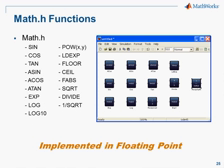Math.h functions are the simple operations you'd expect in the simple C library math.h: trigonometric, log, exponent, inverse square root, etc., as well as the basic operators such as divide. The implementation is multiplier-based, since Altera FPGAs have an abundance of high-precision multipliers.